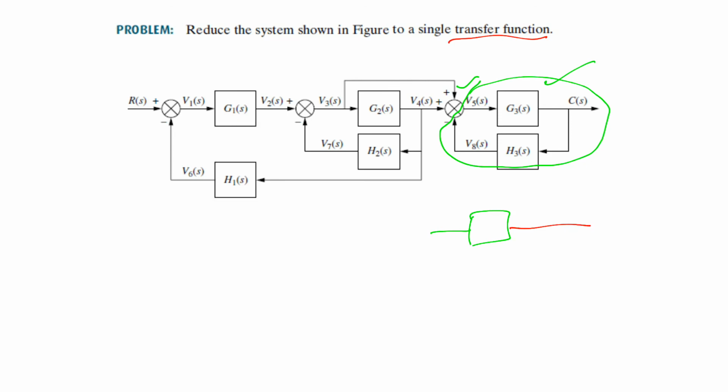Let us suppose that the transfer function of the feedback form is Gf. After that we will see that this is the pickup point, and if we take this pickup point here, then in that case we are left with only these two signals which are in parallel, and we can add these two signals.